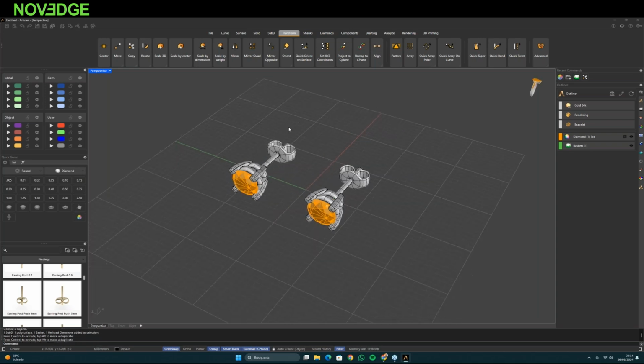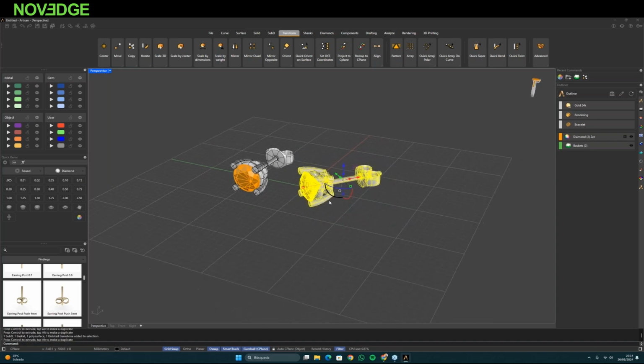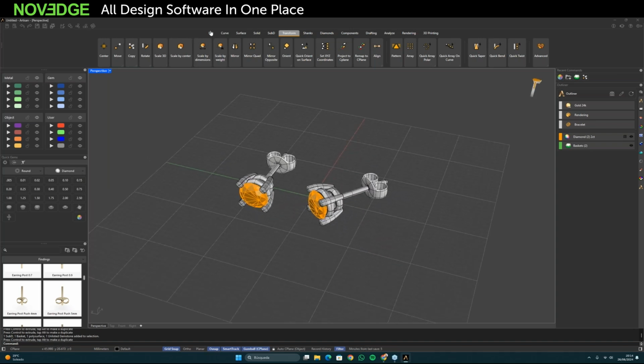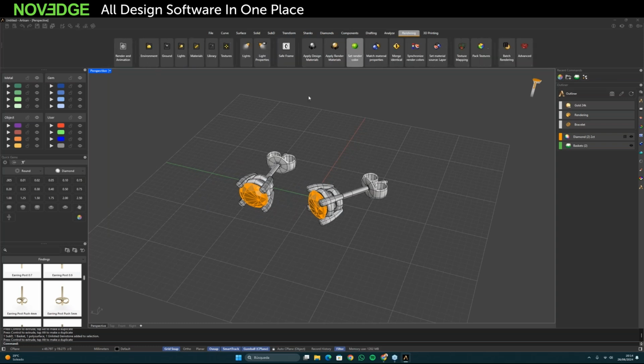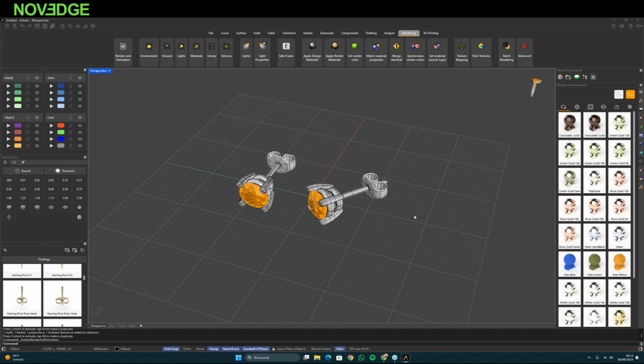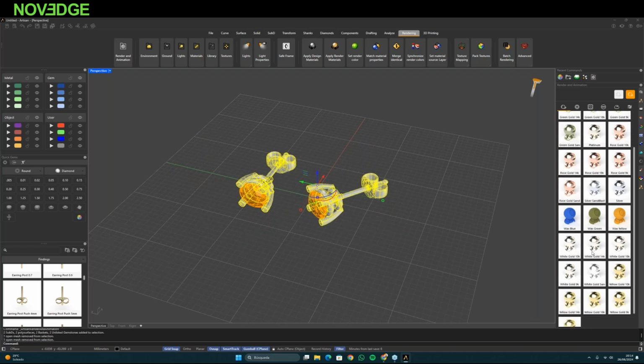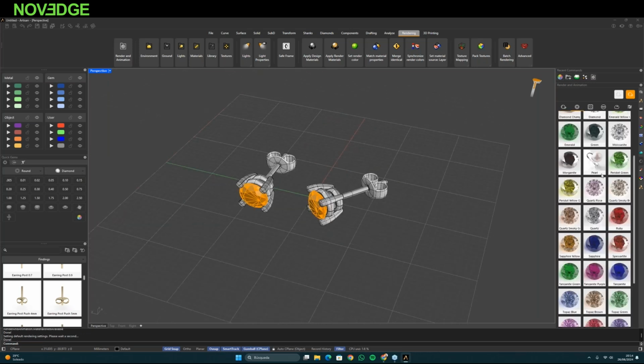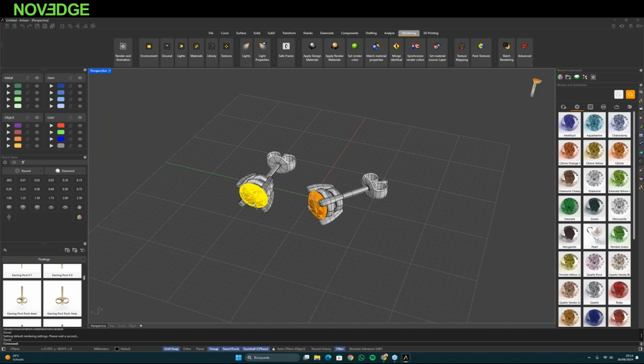And I always like to turn it a little bit just to show the side of the basket, so you can see all the details in one single picture. So let's go to rendering, render animation, and here we can set all the materials. For the metal, I'm going to select yellow gold 18 carats. For the stones, I'm going to choose the diamond just by dragging the material to the stones.